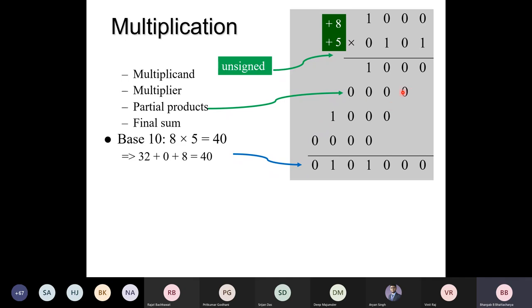And you need some kind of shift mechanism. And then you have these numbers, right? You have so many rows, depending on how many bits are there in the multiplier. So each of them is a binary number. So you are adding multiple numbers, right? You are adding multiple operands. So what can you think of? Addition of multiple operands. With carry save adder. Yes, we have just studied that, right?